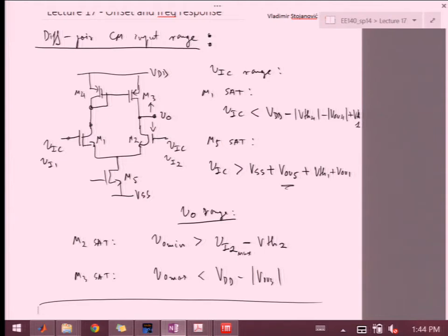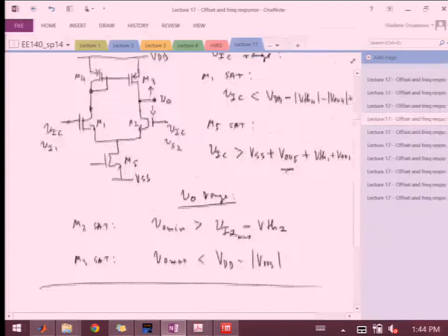Okay. So similarly, if we have the cascode load, then instead of looking at just the VDD, you'll be looking at intermediate biases, and then again calculating these conditions. With respect to the gate voltage, you'll be off by a VTH up or down, and then also you'll have the same issues in the tail, right? Okay.